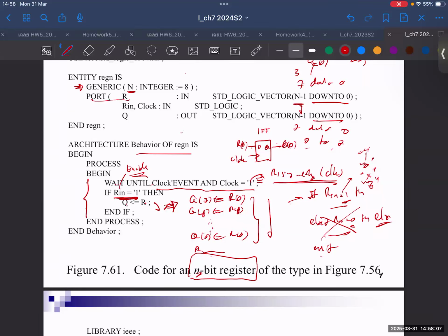And what happened with that? They compiled it for 10 hours, and at the end, they said not enough memory. What does it mean? Everything you miss will generate a nested latch. Nested latch means you have a network of latches trying to do something, and you have 10 levels deep. Every layer multiplies exponentially. That's why there is no memory.